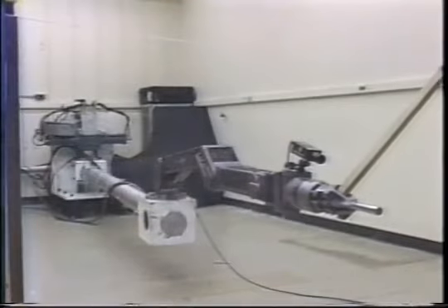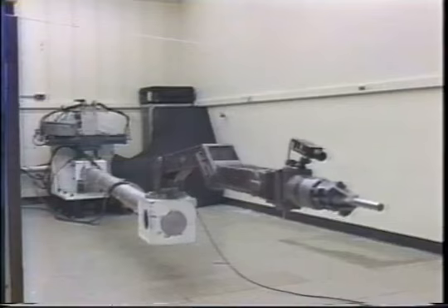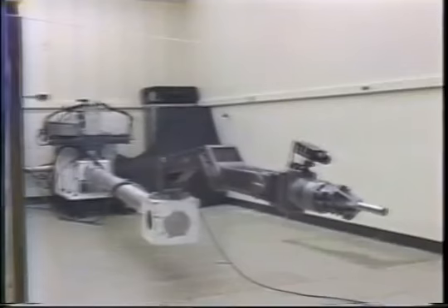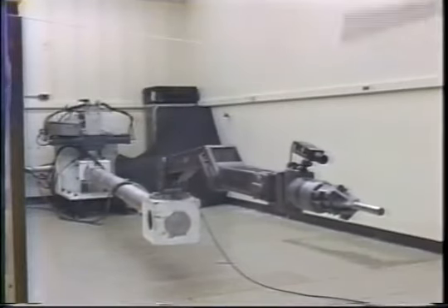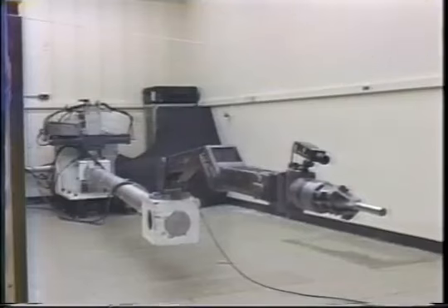If an external impulse is applied at the tip, the vibration in the vertical and horizontal directions can also last more than 1 minute. Again, by applying inertial force active damping control, the controller can damp out the vibrations in less than 2 seconds.